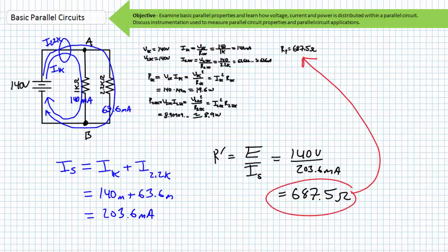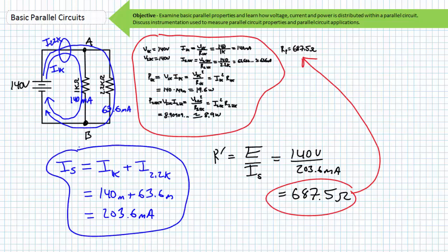That's what we just calculated using the parallel resistance formula. Yet at no point did I directly apply it during this set of calculations. I used Ohm's law, the simple and non-negotiable statement that voltage across elements hooked in parallel is the same, and a pretty understandable observation that current drawn by individual elements within a parallel relationship had to come from somewhere.